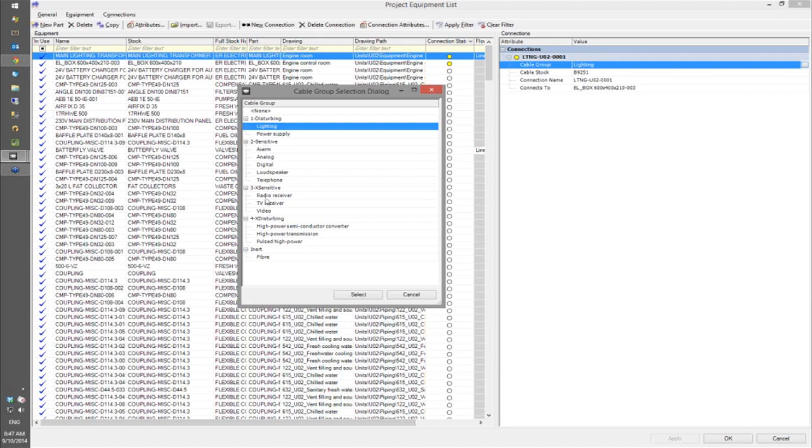My tree here is only two definitions deep. If you really want to, you can go as deeply as you need to get the grouping you want. Cable space groups can be assigned at any level in the tree, and cables at that level or lower can be routed through that cable space.